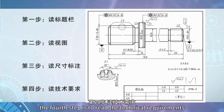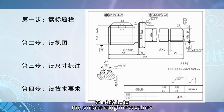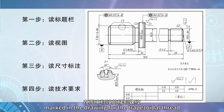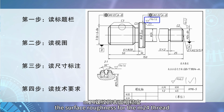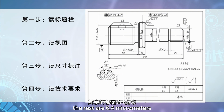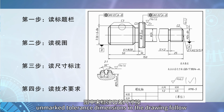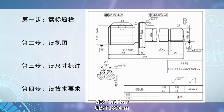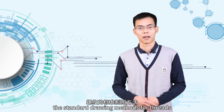The fourth step is to read the technical requirements. First, let's look at the surface roughness. The surface roughness values, marked in the drawing for the trapezoidal thread and the 48 cylindrical surface, are 1.6 micrometers. The surface roughness for the M24 thread is 3.2 micrometers. The rest are 6.4 micrometers. Next is the textual description section. Unmarked tolerance dimensions in the drawing follow GB/T 1804-M. In this lesson, we will focus on learning the standard drawing methods for threads.